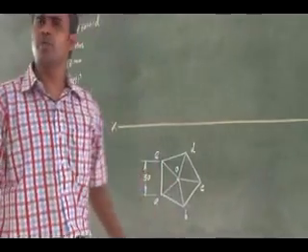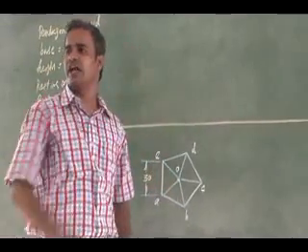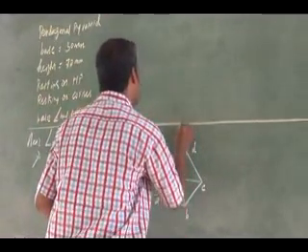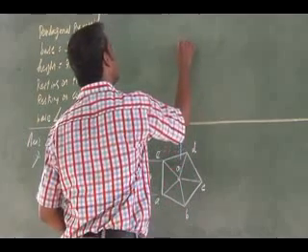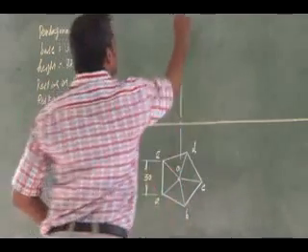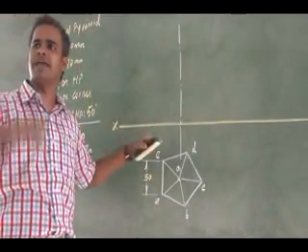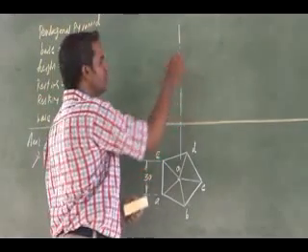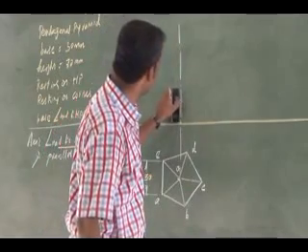Then how do I have to proceed? You project the axis projector line. Along the axis projector line, from the base you mark the apex, to the height of the pyramid. It is 70.